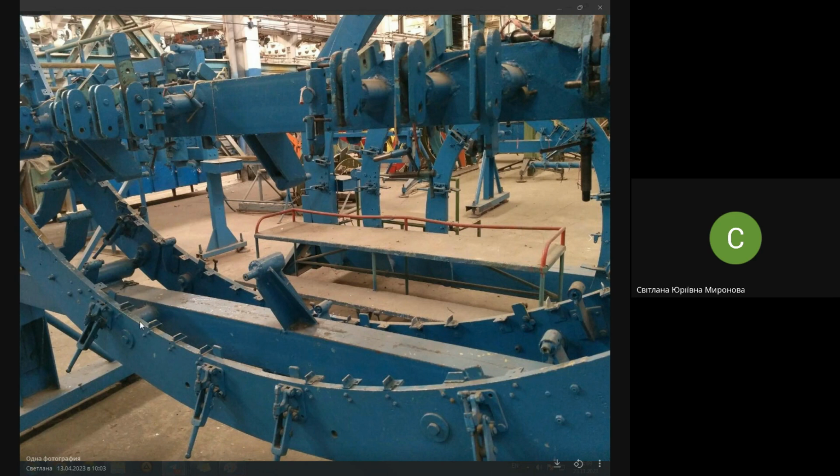They are locators for knees. They imitate pieces of stringers, and knees would be placed, no, as we did not include knees into your frame. Maybe we think that they are any panel, or that we don't need them at all. Here it is visible that in this frame the knees are located by special locators of contour also, something like a stopper. And those things that you see, a rough structure, let it be, with a barrel at the end and a bushing with a hole, it's the locator of CFH.